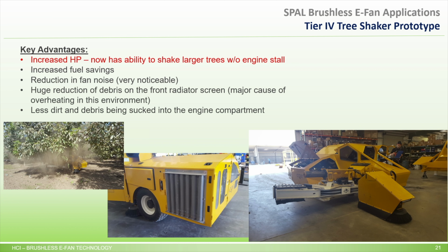Huge reduction in debris in front of the radiator screen. For this industry, that's a major cause of overheating. And then also less dirt and debris being sucked into the engine compartment. When we got back after a full day of testing in that nasty environment, they usually like to open up the engine compartment and wash it out. But in this case, they opened it up and there was no dirt and debris in there. Again, because the fans are not running at full speed, sucking all that dirt into the engine compartment throughout the day.